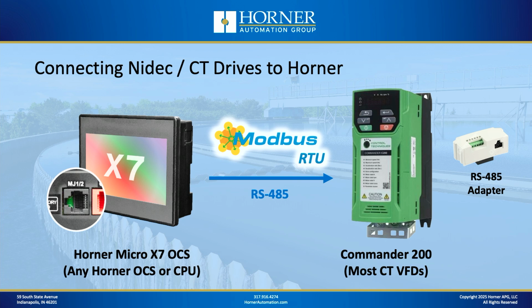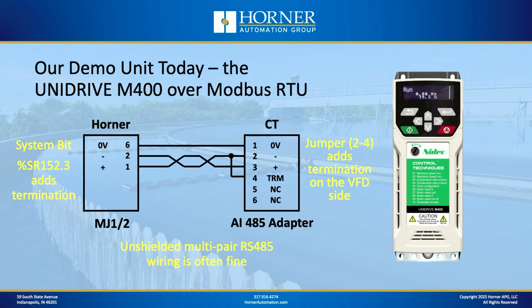However, for those of you who prefer to use Modbus TCP over Ethernet, our entire content today is pretty much applicable to you. You can just skip over the parts where we talk about specific serial port settings. That's one of the parts we're going to talk about next, our specific serial settings. When we're talking about RS-485, we're talking about twisted pair wiring.